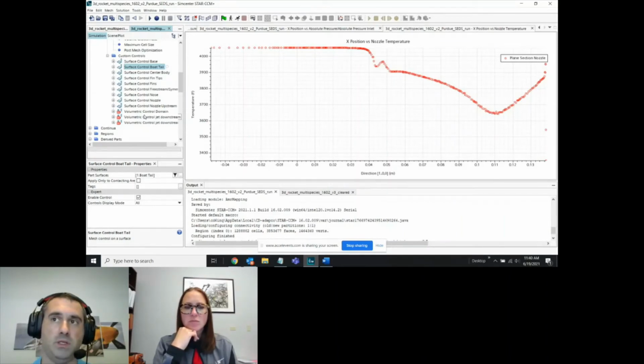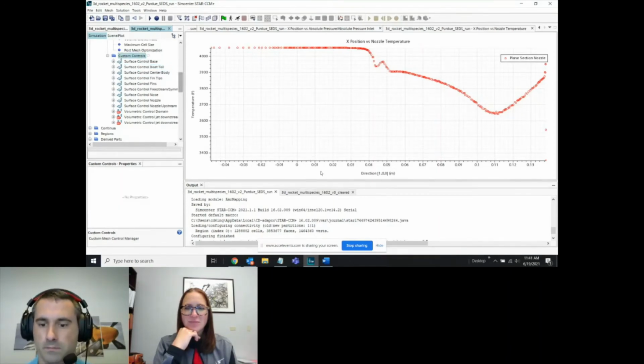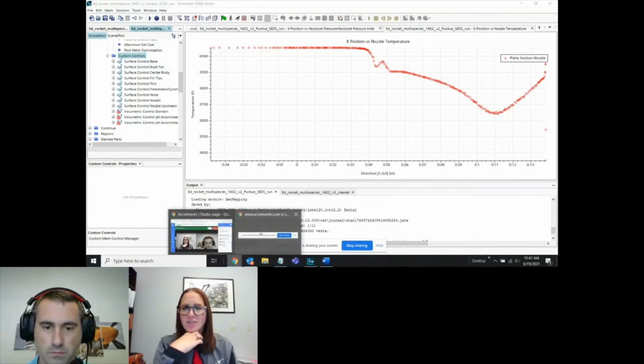You can also change how much the adaptive mesh refinement is refining shock waves and things. So that's completely all open to your control. But the nice thing about this is it's baked directly in the simulation, so you're not having to mesh and import it in. It's all directly here right in front of you. So hopefully that answers your question.